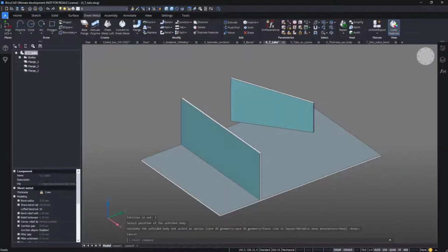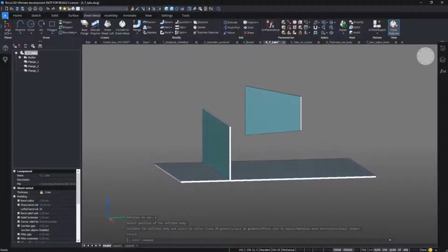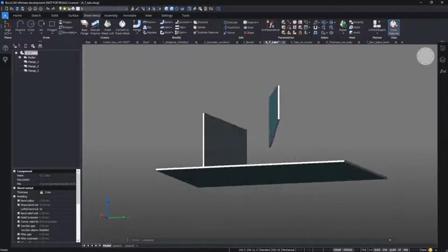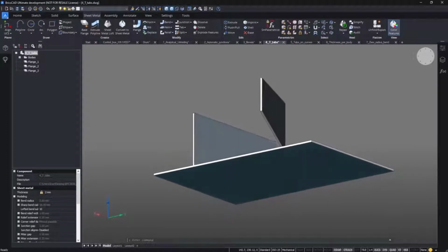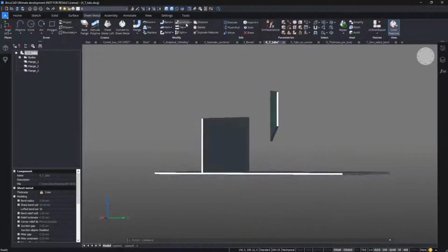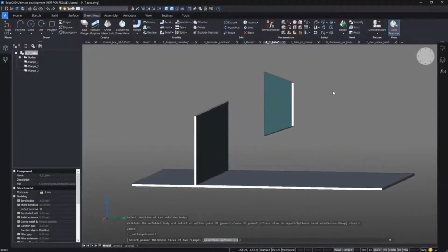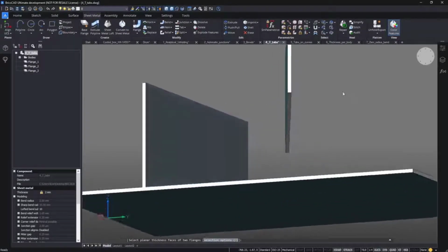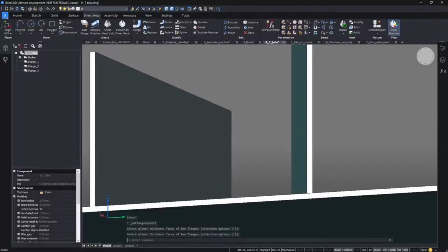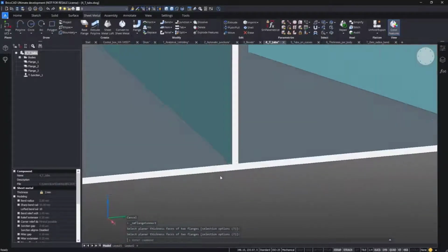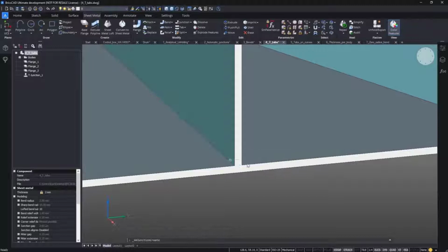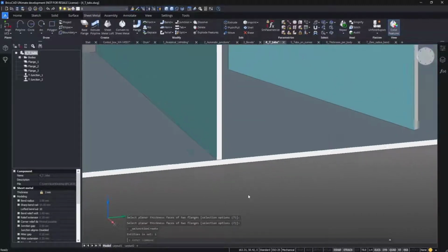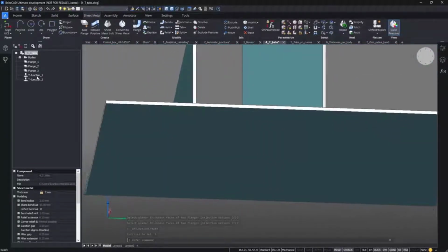We have now the possibility to create tabs and slots inside a flange. We call this feature T-tab. It is necessary first to create T-junction. We can start from two different parts wherever in space that we connect to create the T-junction. We can as well create it from a single solid. We get automatically two parts. Those junctions can be switched to tabs and slots.